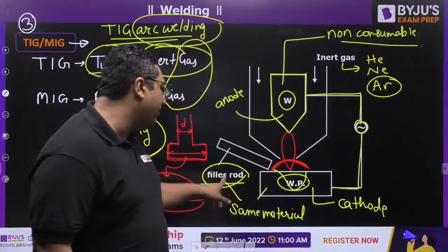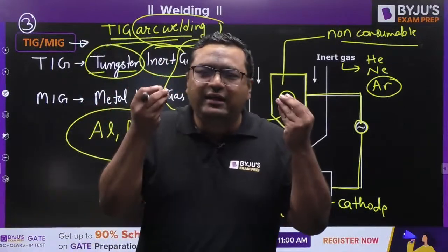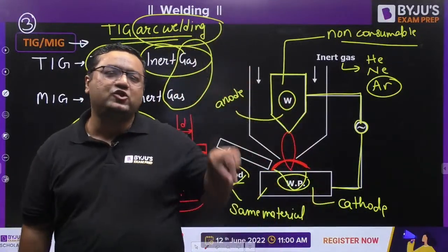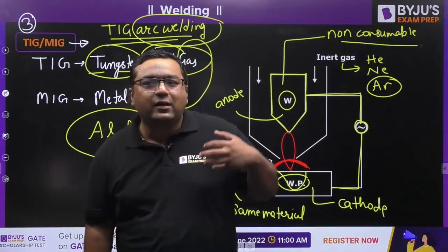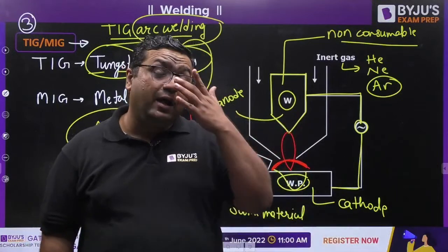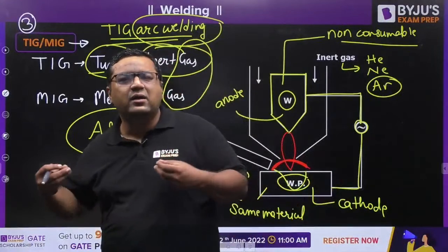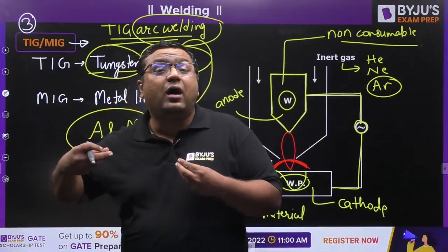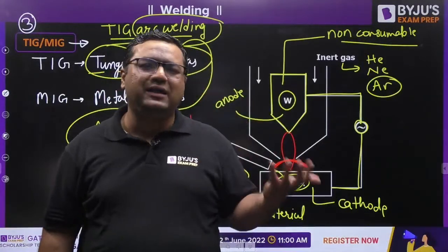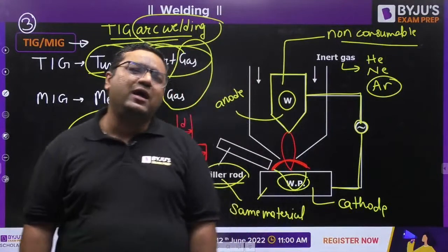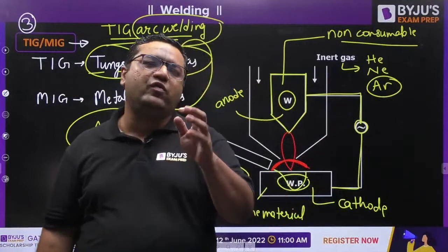So my dear, here only 1/3 part of the energy is coming. For less amount of energy you can weld very thin plates. That's why plates of 8 to 10 mm thickness of aluminium and magnesium only are getting welded by this process, and that is why we generally do not require any extra material to make a weld bead, because the thickness of the plate is very less, so more material is not required. We are joining very thin plates of 8 to 10 mm.